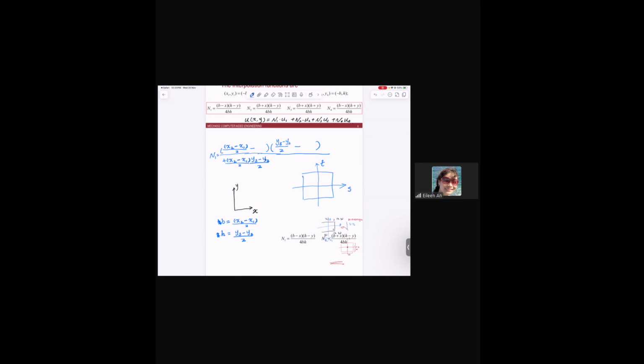And then we can use this kind of shape functions to do the calculation. But for this one, N1 equal to b minus x times h minus y, right? And in this new coordinate system, this is b, this is h. And we need to use b minus what? Is that x? Yes, x, right? Because we used a new coordinate system.